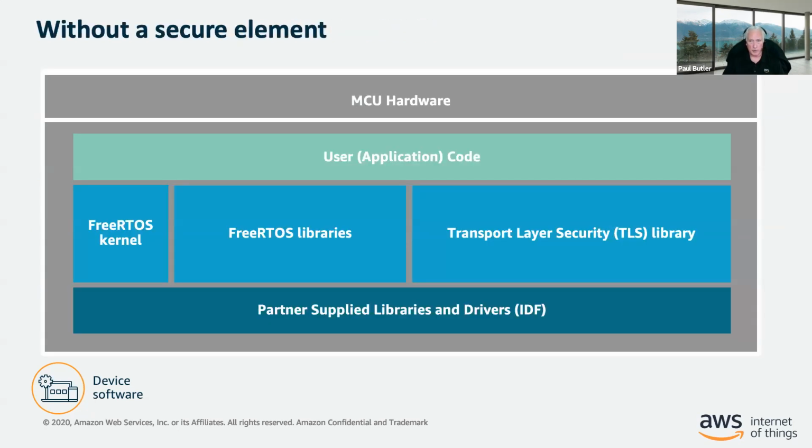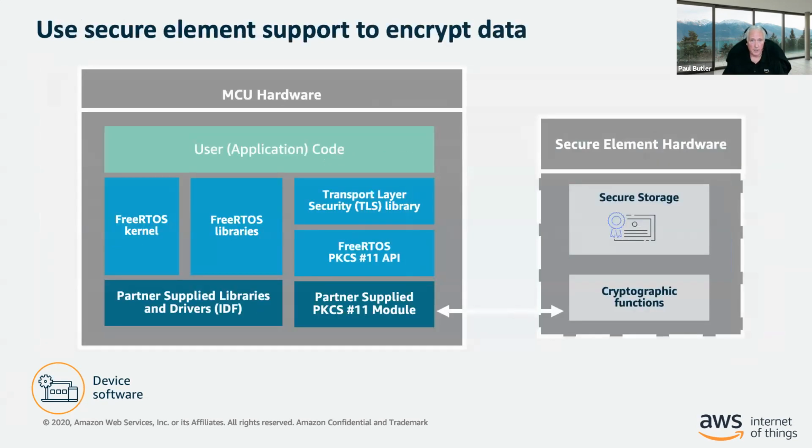And this is a picture of what it looks like without a secure element. You typically would have to store your keys either in your user code on the flash or somewhere in your device. And if the device is physically accessible, well, that is a potential risk. People could tamper with it and maybe discover that. If you're using the secure element, then you have that secure element hardware off the microcontroller core, and you have secure storage, and it's far less tamperable, I guess you could say.